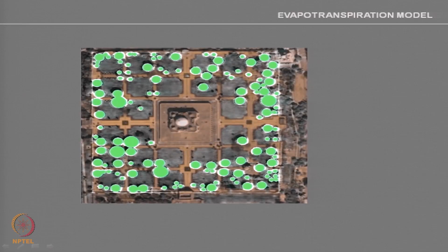So, in other words, what I am trying to point out is that you can modify the surrounding environment of the building, bring down the temperature, but remember it increases the relative humidity, obviously, because a lot of evaporation occurs from the green trees, etc., but one can modify this.